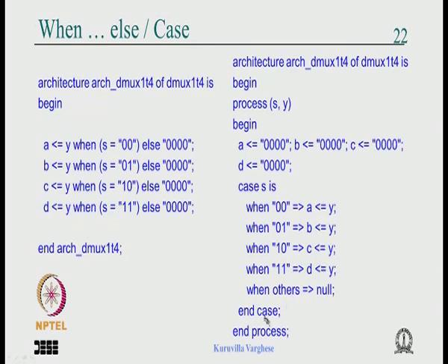So this is perfect, but then you can write if also, because instead of case you can write if, though it has a kind of priority. But since these are mutually exclusive and you specify all the conditions in if, it is redundant.